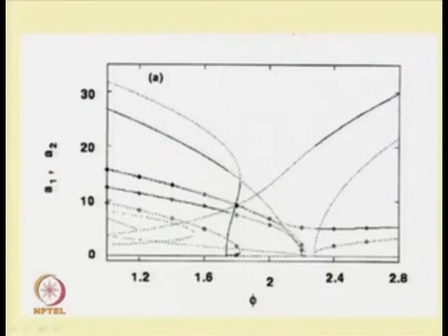By checking each equilibrium point and studying its stability, one knows whether the system is stable or unstable, and by varying this control parameter one can find the bifurcation points. In these cases, this is a pitchfork bifurcation point. This is a supercritical pitchfork bifurcation point, as from a trivial stable response we are getting a non-trivial stable response.